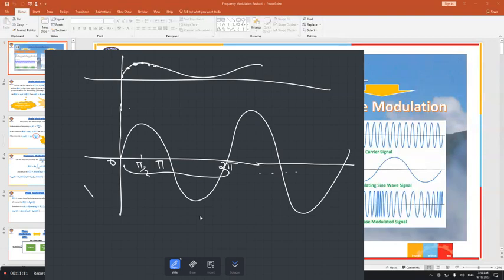This is called angle modulation. Are you not modulating your angle there? Every instantaneous angle of the carrier wave is now modulated according to the instantaneous amplitude of the message signal. Have you understood this? This is called angle modulation. Now, what is frequency? A rate of change of the phase angle is going to give frequency, yes or no? So I can relate this angle modulation to frequency. Hence, it is frequency modulation. We call it frequency modulation. Have you understood this?